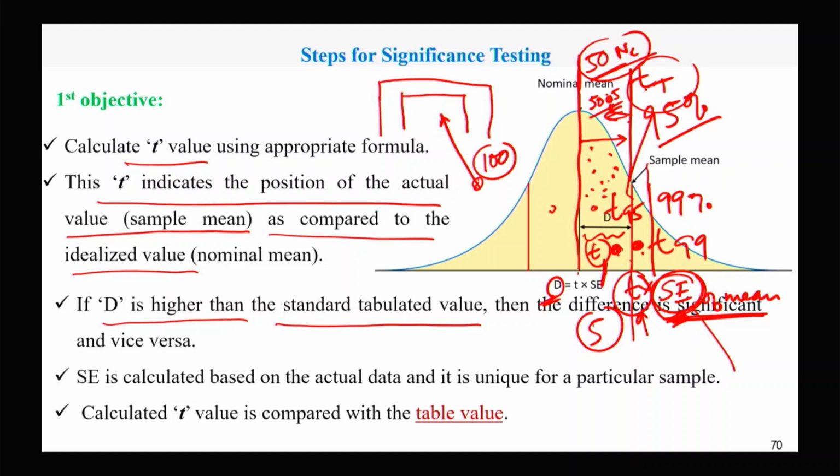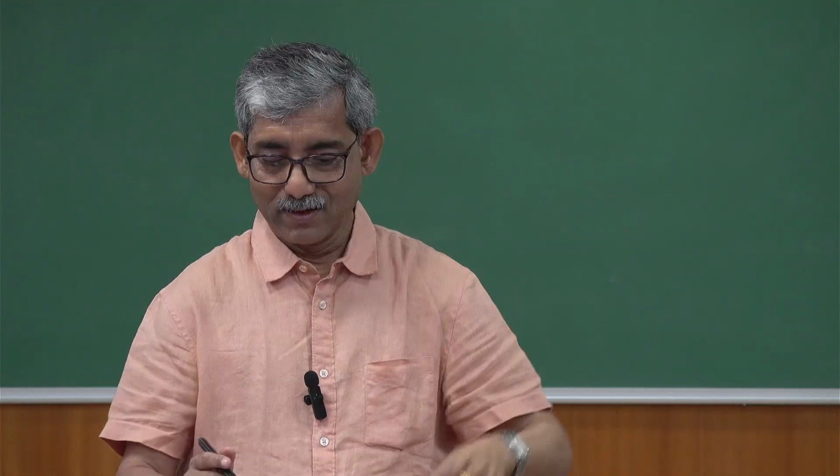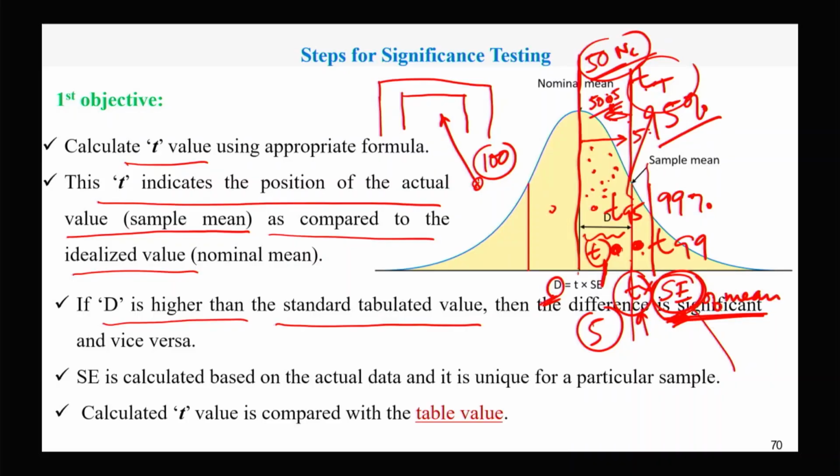So we should not bother, and we should not target also to produce exactly 50 any. Now it is say 51 at this point, that means it is crossing the 95% level. Crossing the 95% level means whether we should take action or not. Sometimes we don't take action, it's a warning, but when it is crossing say 51.5 at this point, then it's basically significant.